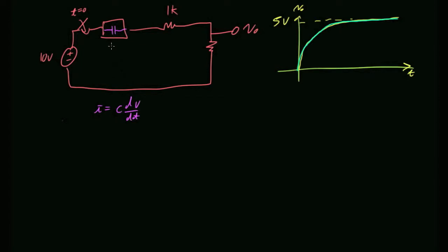Okay, remember, we looked at those. We looked at a parallel plate capacitor, and we said, once it charges, there's no movement of ions. If there's no movement of ions, there's no current. So eventually this cap will charge. When it charges, there'll be no flow of current, and when there's no flow of current, it's basically just like an open circuit. So tell me, what's this circuit going to look like? What's my output voltage going to look like if that cap charges and there's no current?